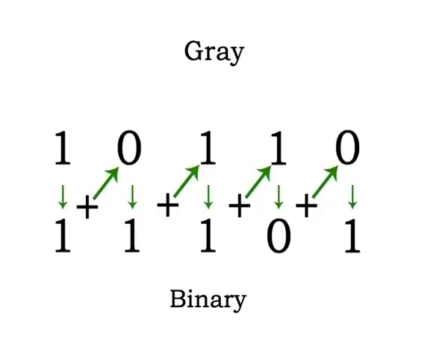Gray to binary conversion. To convert from Gray code to binary, use a similar method. However, there are some differences. The following rules apply. The most significant bit, that is the leftmost in the binary code, is the same as the corresponding bit in the Gray code. Add each binary code bit generated to the Gray code bit in the next adjacent position. Discard carries.